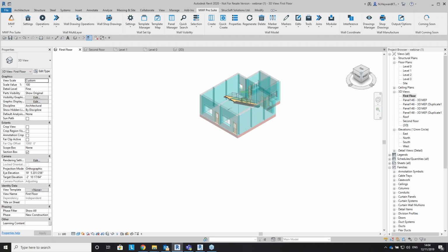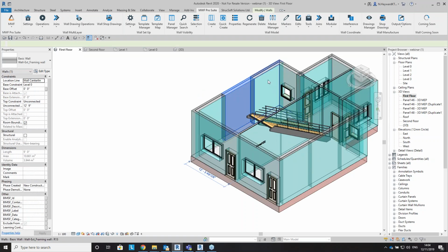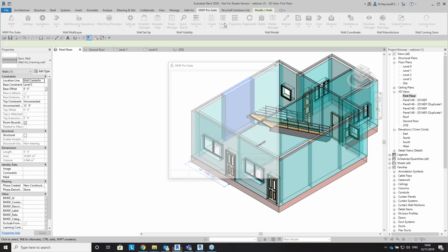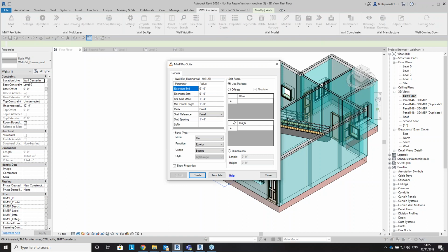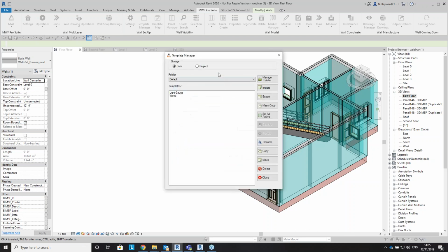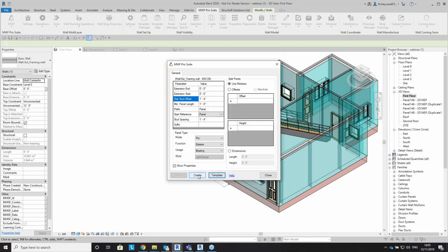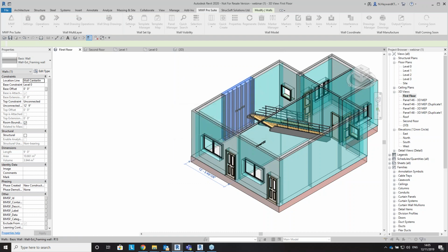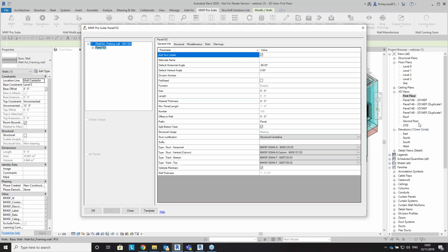So let's start now, and this is more of the manual way to create one of our walls. I've just grabbed one of these walls, clicked into the wall module, and now I've got this screen come up where I can specify some offsets and then show the type of the wall. And now I've got some of my preset templates. So I'm just clicking into this one. And then immediately your properties options come straight up. There are a lot of different things we can add to our panels in this, and we're going to take a quick look at that a bit later.